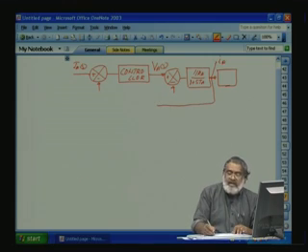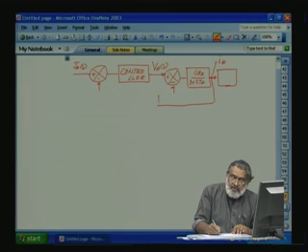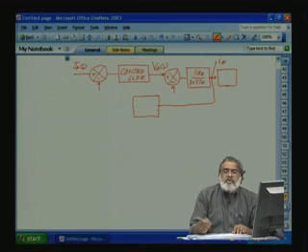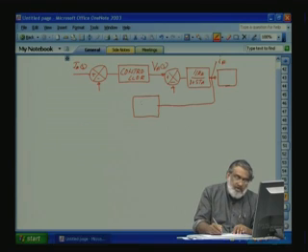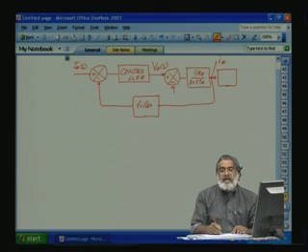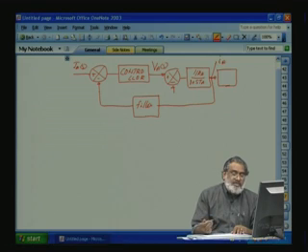This current from the machine has to be stepped down, and because of the switching there will be ripple. Here we are dealing with DC current, so a filter is also required. The transfer function for the filter is a simple first order filter. So IA is required, and this inner current loop is required.